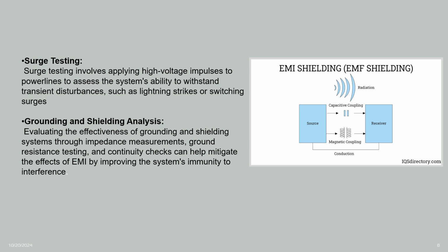Surge tests are critical because they are the only tests that find turn-to-turn insulation weaknesses. These weaknesses start at voltages above the operating voltage of the motor and are precursors to serious failures and shutdown of the motor. Such tests are also used to find hard shorts and a number of other mistakes in windings and coils.